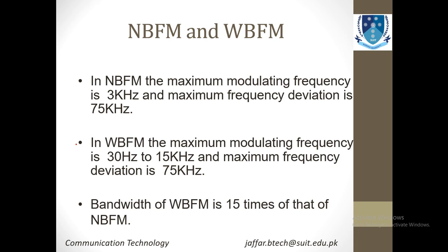But in wideband FM, you can see that the maximum modulating frequency is 30 Hz to 15 kHz, and the maximum frequency deviation is still the same. So the only difference is the maximum modulating frequency spectrum. In NBFM this was 3 kHz, and in wideband FM your input varies from 30 Hz to 15 kHz. We have a large range of modulating frequency, and the bandwidth of WBFM is 15 times that of NBFM.